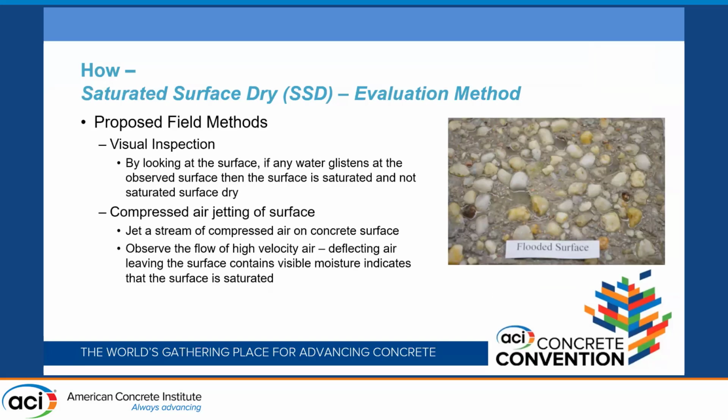There are also field methods from committee members. One is visual inspection, just by looking at the surface. If there's water glistening at the surface, then the surface is saturated, not SSD condition. The other way is to jet a stream of compressed air on a concrete surface with a cardboard at the back.